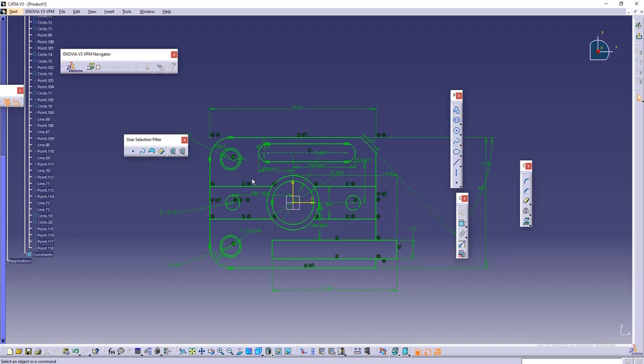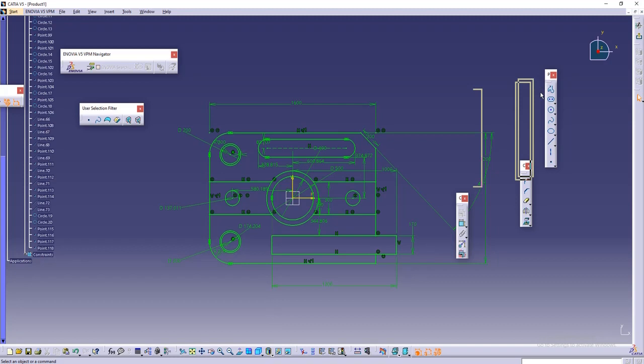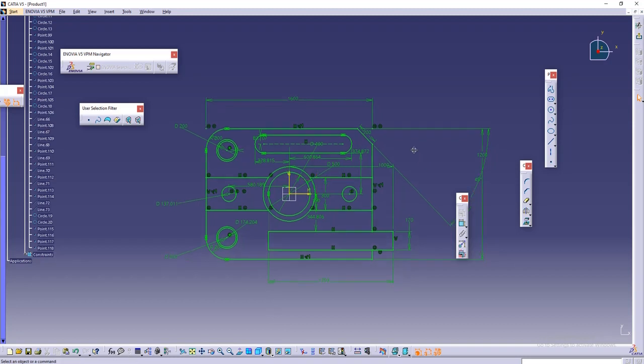So this is the first assignment you need to create. You need to apply all the tools here of the sketching workbench, use the dimensions and try to constrain everything. Do not over constrain anything, because if it is in pink, you will understand that this is over constrained. So all the sketch has to be in constraint mode. So this is the basic first exercise.